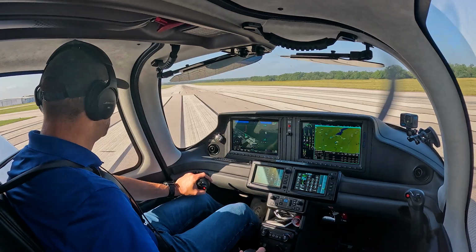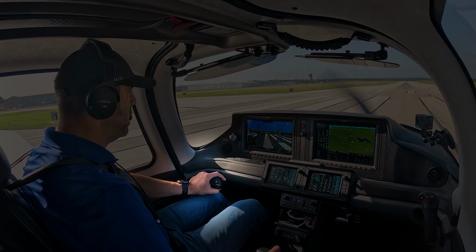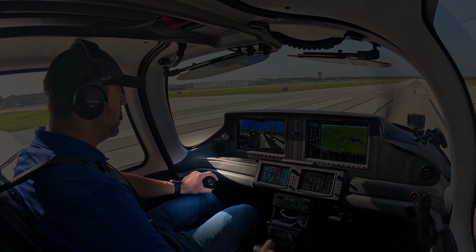So knowing this information, what's our crosswind correction going to be for takeoff? With a crosswind from the right, we're going to apply full aileron deflection into the wind, so that's a right aileron. Now the P factor and slipstream from the propeller hitting the tail, we're going to need to apply full right rudder as well until we gain speed and control surfaces become more effective.